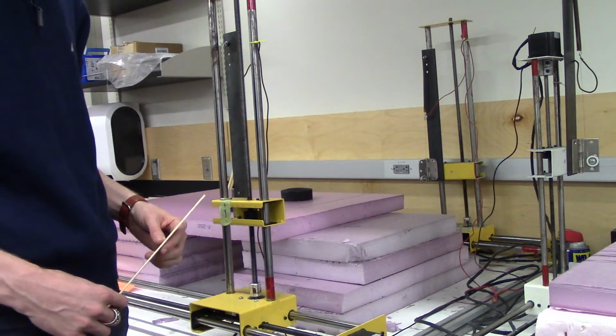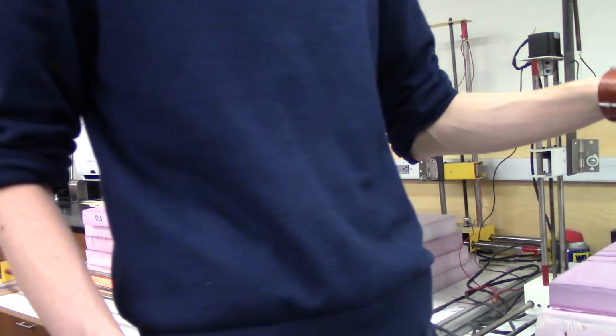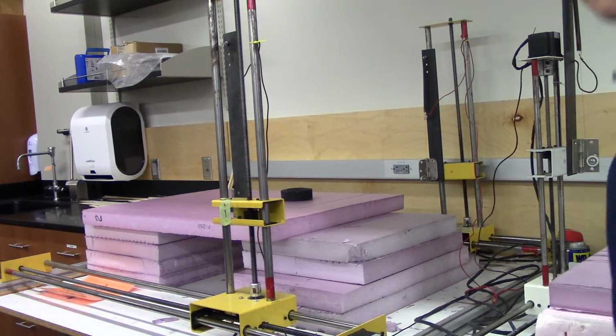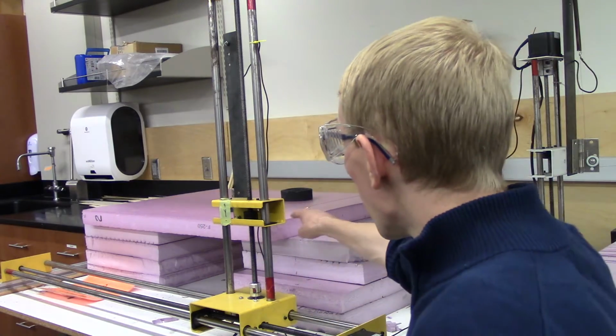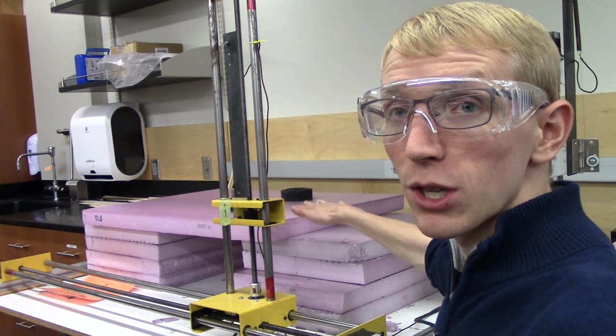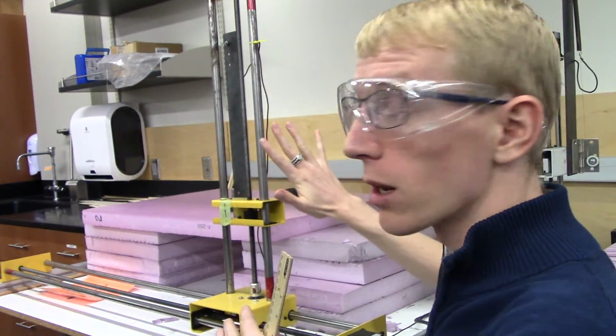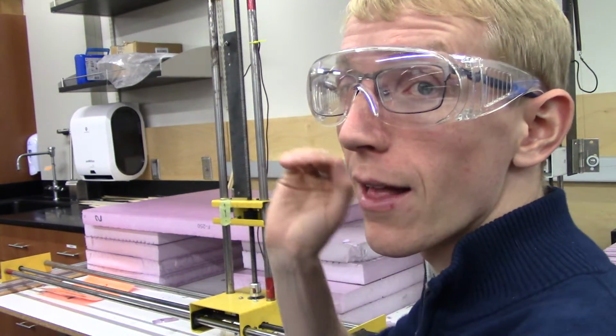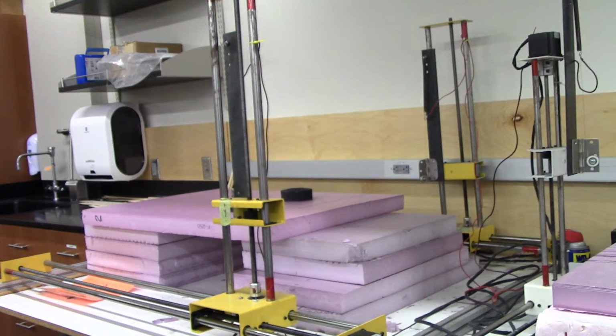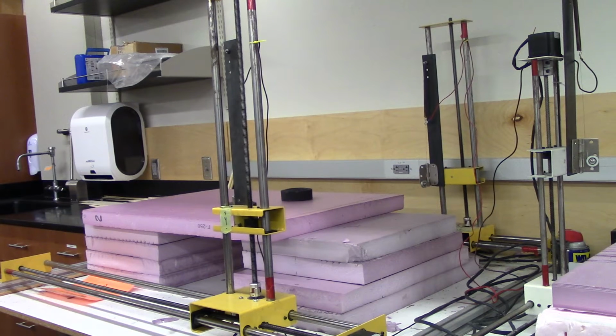But here, the first thing we're going to do, I'm actually going to come over to the computer and eyeball, getting nice and low here to see where the wire is equal to the foam on both the left and the right hand side. Now I want to try to make that as flush as possible, so I'm going to come back over here and measure it to make sure that's correct. So here on both keys, I'm moving them down so that the wire is just barely above my foam block. Move down one side just a little bit more than the other. Those look about center on both sides.